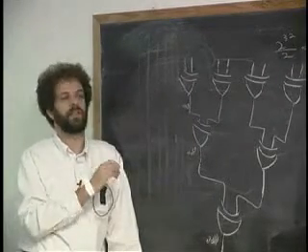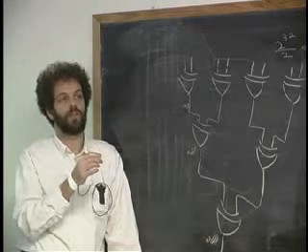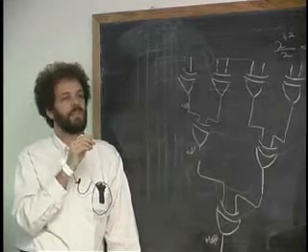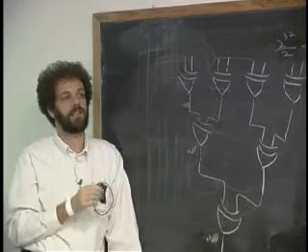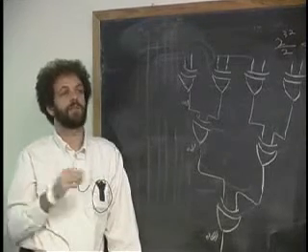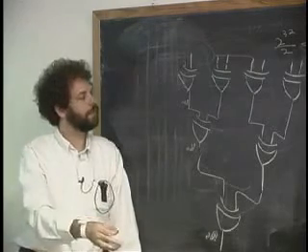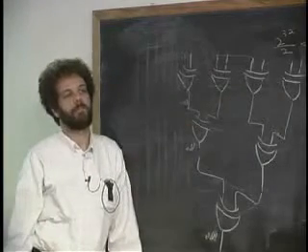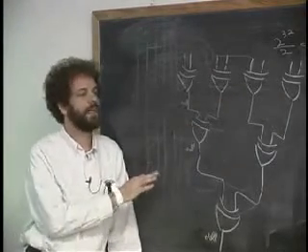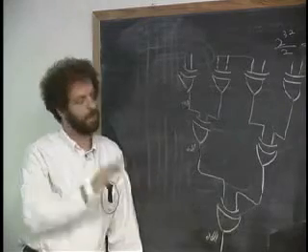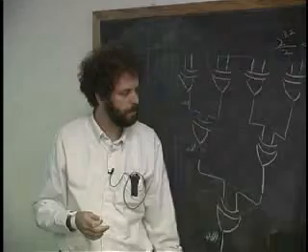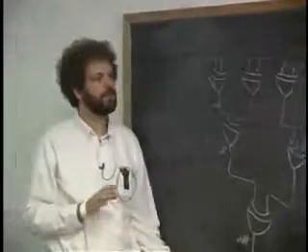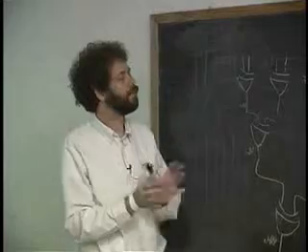Draw me the sum of products of 8 inputs. 2 to the 8 is 64, right? So I'm going to have 32 AND gates and an OR gate with 32 inputs, which is a huge structure compared to this one with 1, 2, 3, 4, 5, 6, 7 parts in it. Much smaller and much faster too. Okay, so the big message here is that Karnaugh maps and sum of products are good, but don't get fooled into thinking that that's all there is. Often there are other forms which are in fact better, depending on the function.